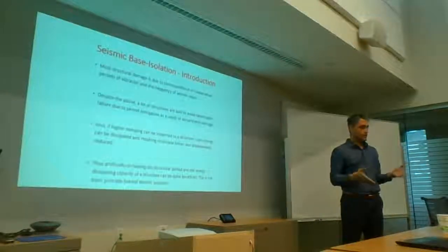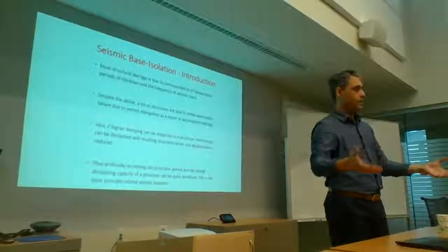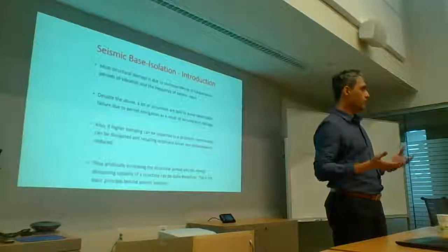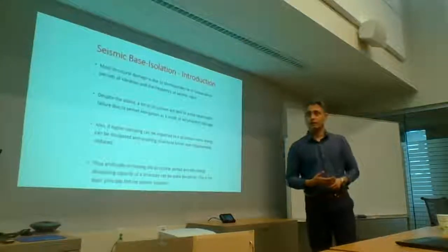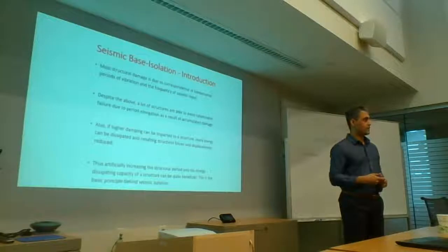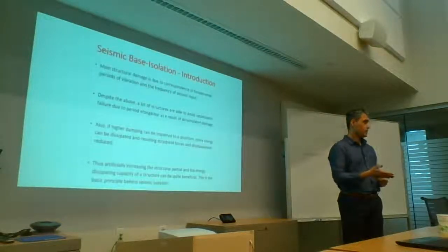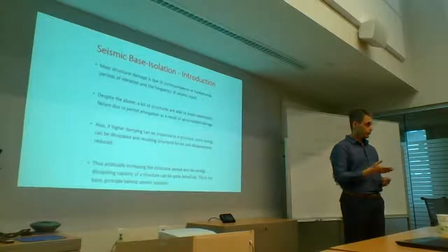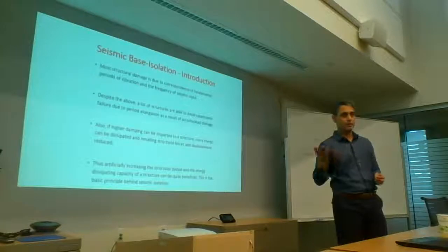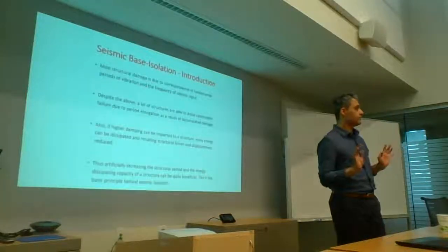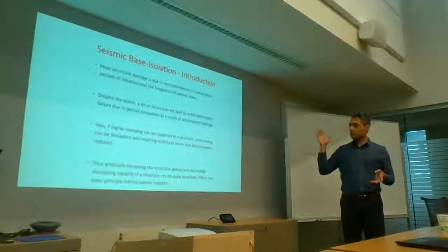So a lot of the structures, they're able to avoid that sort of catastrophic failure for different reasons. One could be that you have short period energy, and in a neighborhood you've got these tall buildings, or vice versa. You could have damage because of that. And that's why I'm saying in Victoria, for example, if there's a crustal event which is quite rich in short period, high frequency energies, we've got lots of unreinforced masonry, single story, 2-story buildings. They're going to vibrate at like 0.3 seconds. That sometimes wakes me up at night. But that's that now.